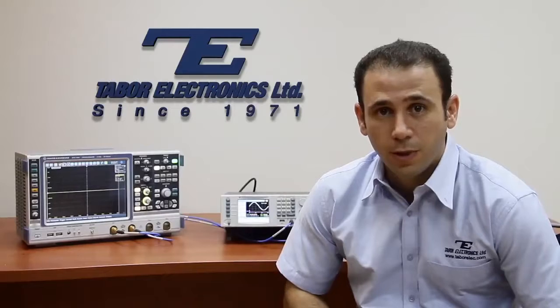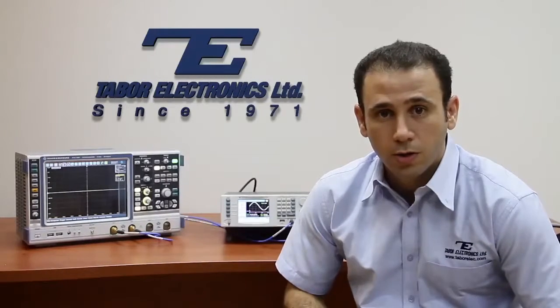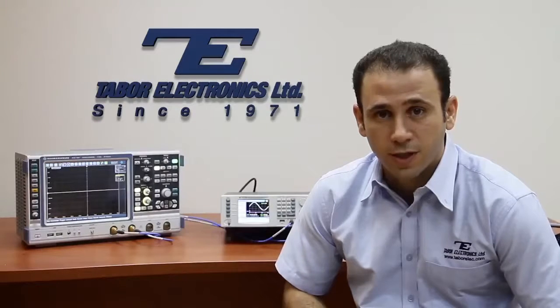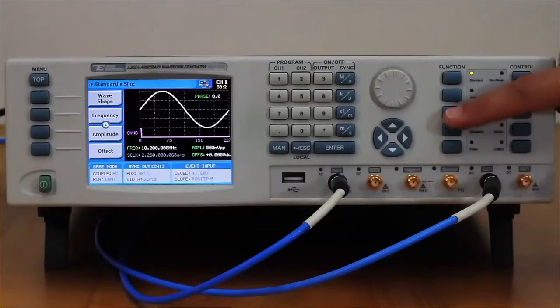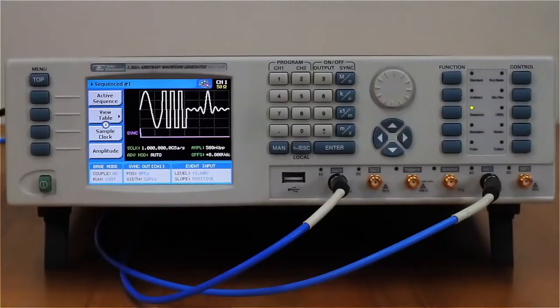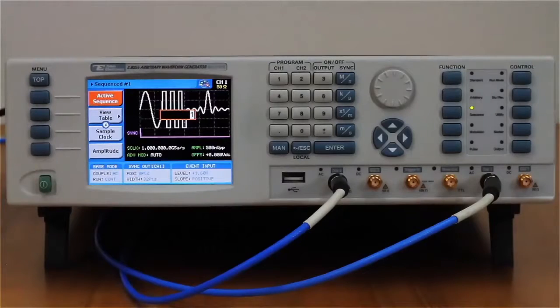The first step to build a sequence is to download your waveforms into the different segments, or to split a large waveform into several segments. Once that's done, we can build our sequence. To begin, press the sequence button in the function menu. A new set of menus appears on the screen. Press the active sequence menu button to select the index number of the sequence to be defined.